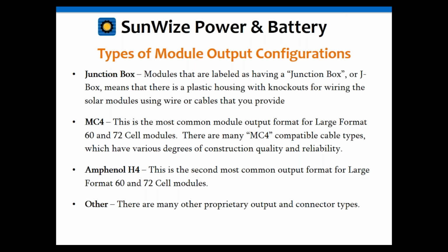Okay, along with the different types of modules, they have a couple different connection options. Most of your Class 1 Div 2 modules, and let me talk briefly about that as well. Class 1 Div 2 hazardous rating modules are going to have a junction box on the back of them. A lot of your smaller ones will as well. Those junction boxes allow you to connect with a cable and/or conduit. You're going to make actual terminations either with ring terminals or with an actual box lug inside the junction box. So it's going to be an actual screw terminal in there for you to connect to.